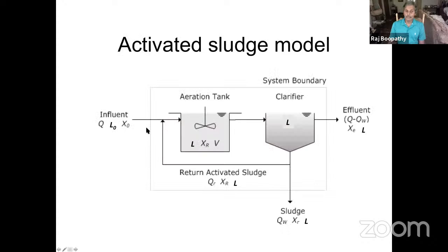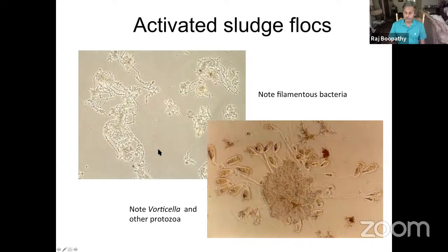You can calculate how much wastewater is going in, how much is collected, and how much is retained in the form of sludge. You can come up with your own HRT and SRT in your system. It's just a simple calculation of the volume of the reactor and how much time it spends. You can calculate how much sludge is produced, how much sludge is being recycled. Okay. So what is doing the job?